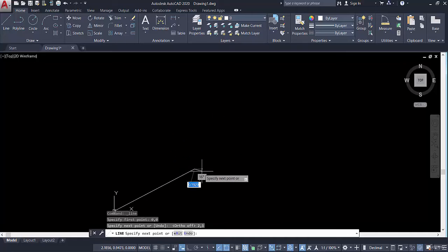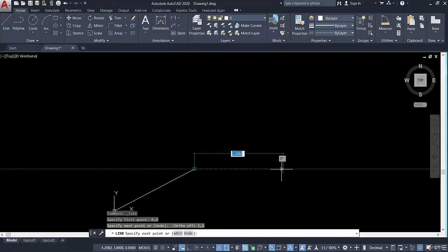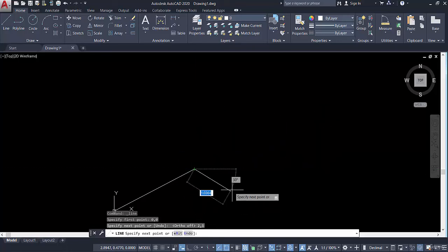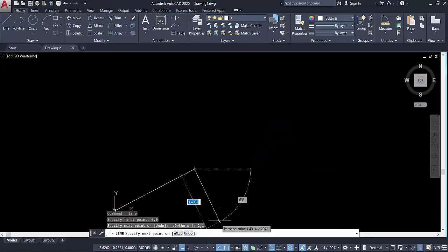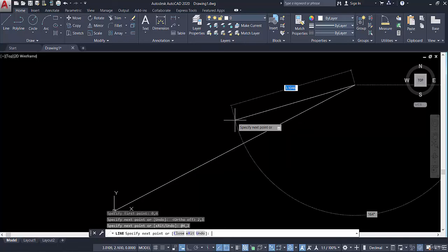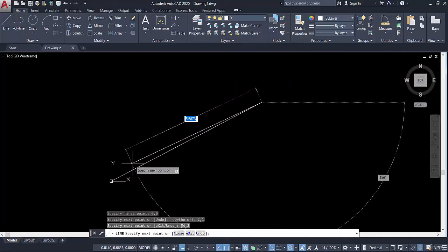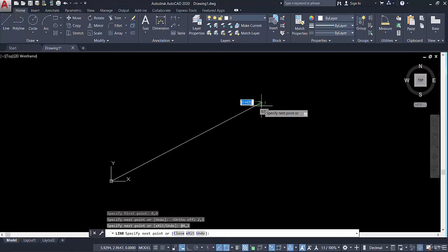So we can make this point our new origin for the next point if we want to continue with drawing. How can we do this? We hold the press on shift and type any coordinate. So let's put 4, for example, 2. We can see that the second point we draw has the first point as its new origin.